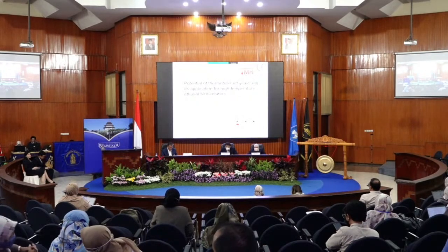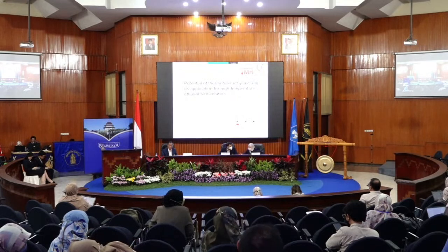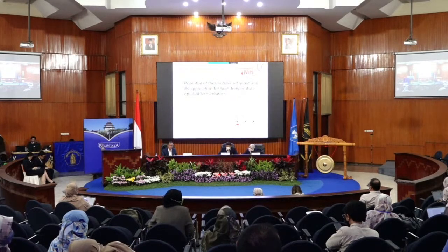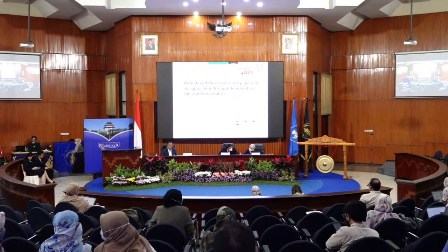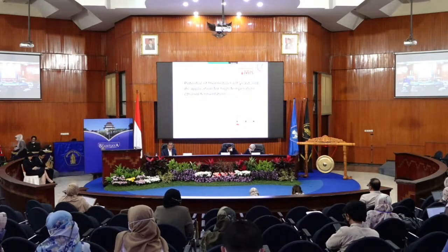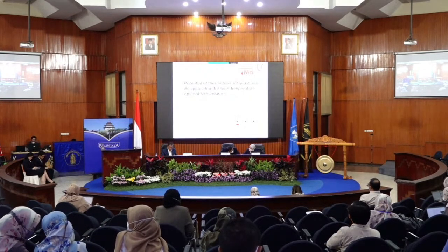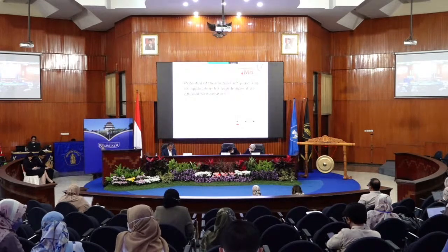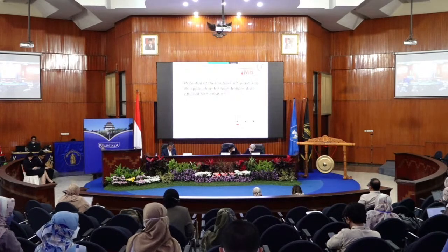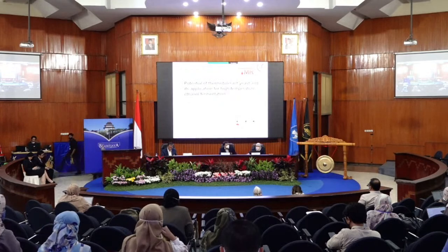This high temperature means around 40 degrees Celsius. But if you use Saccharomyces cerevisiae, the temperature should be kept around 30 degrees Celsius. So it is about 10 degrees higher temperature fermentation.